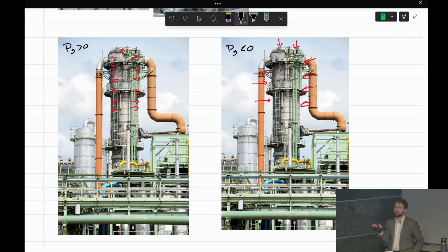The design guidelines are much more stringent if you have a vacuum vessel. In some cases, the chemical engineers say we need that to be at a vacuum pressure, so as mechanical engineers we have to figure out how to design things under vacuum. Like I said, there's a stiffening effect, but it can get quite complicated. So it's important to distinguish whether pressure equipment operates at a positive or negative pressure. Any questions about that example?